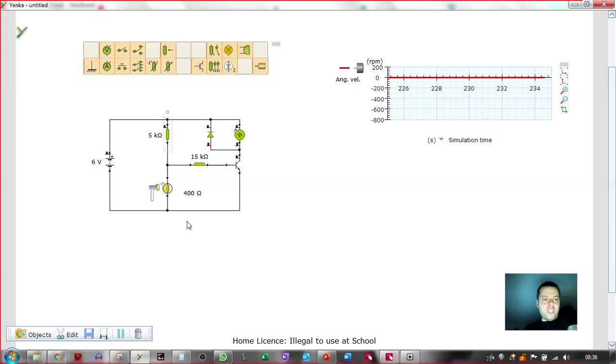So here we have a circuit, and hopefully you guys should know exactly how this circuit works at this stage. We've got a darkness sensor, and that's feeding a signal to a transistor. The idea being that when it's really dark, we should saturate this transistor and the motor will come on. So this could be something like automatic blinds again, right? I'm just sticking with simple,